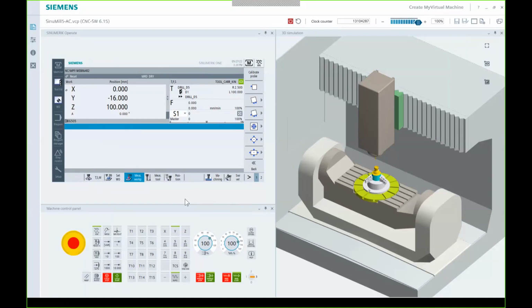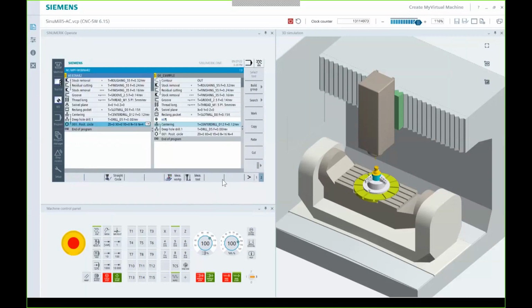So, we got another one that just popped in here. Do you have any limitations with the measuring cycles? No, not in a mill turn. Yeah, I mean the full library is available to you certainly in auto. Obviously, you have the additional cycles there in jog that Dan was just mentioning. So no, you should not have any limitations: all your edge detection, all your corner detection, hole detection, your boss detection, any of your 3D detection. It's all still available to you in auto.